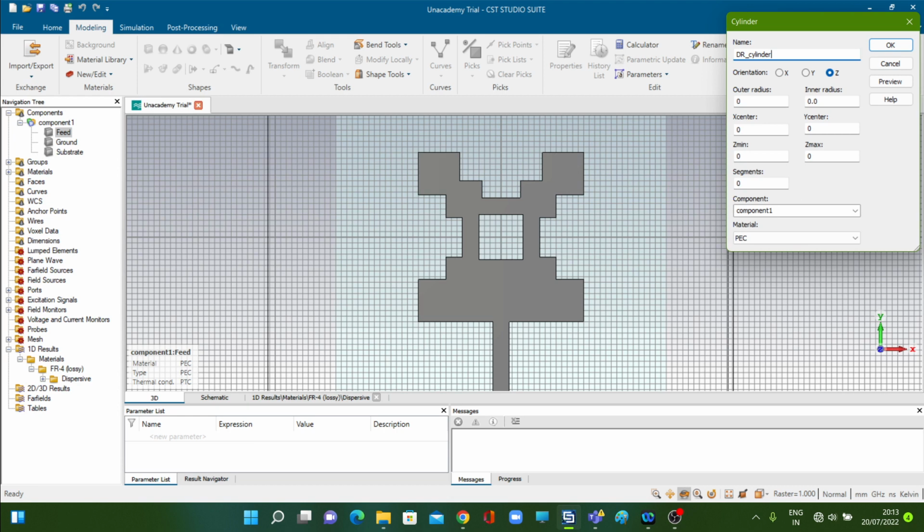In this case, we are creating a solid dielectric block only. We are not creating an annular block. I will show you how to create an annular block later. But for the time being, let us select that we are designing a solid dielectric block only. So the inner radius will be 0. Outer radius will be such that it hides the central slot completely. So we will select this outer radius to be a bit more than the periphery, which is -4 or 4. So it will be higher than 4. Let us select the outer radius to be, say, 6.